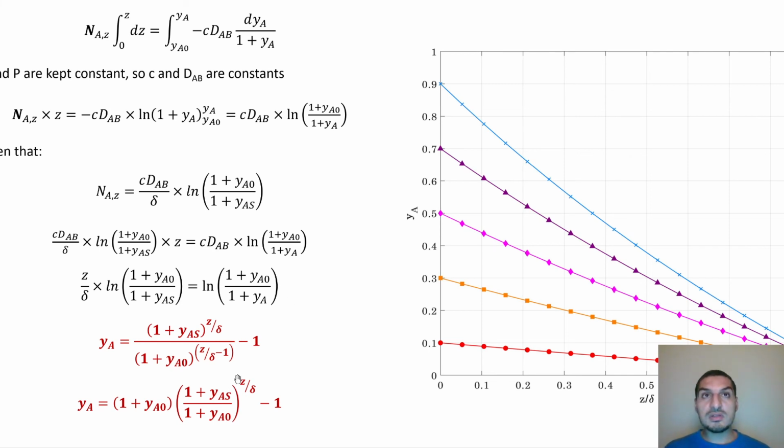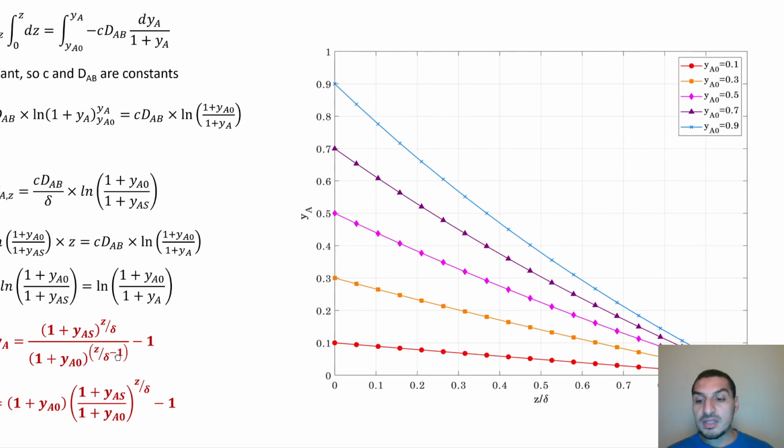One reason is that it's not going to have dimensions, so you don't have the issues with writing the units. The other is that it has limited maximum and minimum values. So no matter how big or how small the delta is, z over delta will start with 0 when the distance is 0, and with 1 when z equals delta.